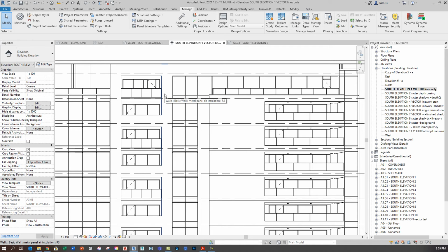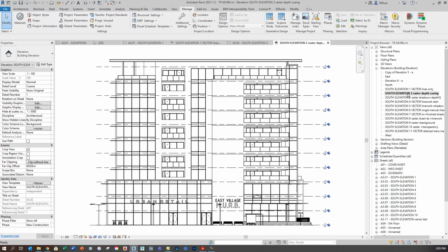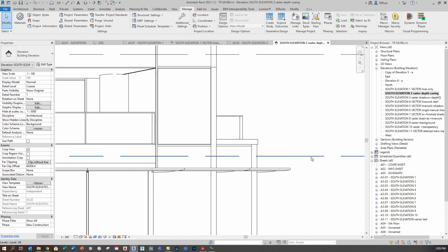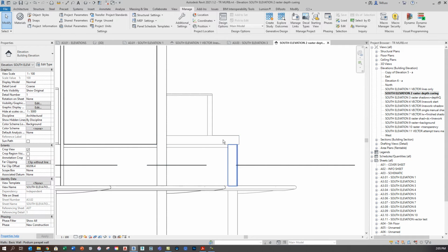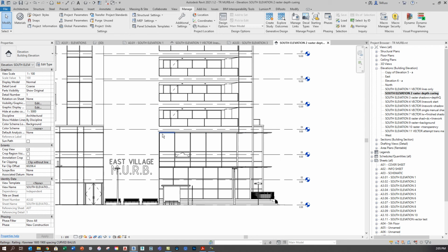So we're going to look at another tool that we can use here to add that emphasis. And maybe before I get to that, I'll make this point about a tool that I'm not going to use, which may have come to mind when I started talking about this topic. You'll notice in this particular view, as I pause there and let it refresh, that these elements in the background are gray, so that certainly would help. The heavier, more emphasized black lines in the foreground will advance towards the viewer, while these ones recede away from the viewer.